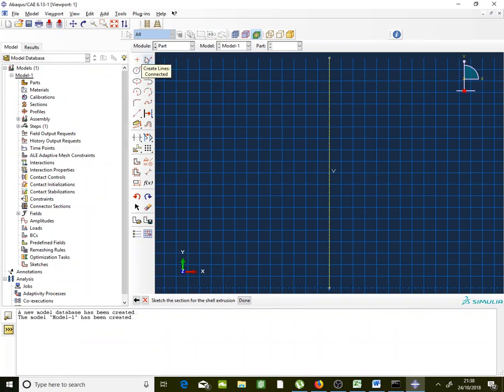So you click on the line again, so it is 50, comma, 100, enter, and then minus 50, comma, 100, enter. You click on cancel procedure.